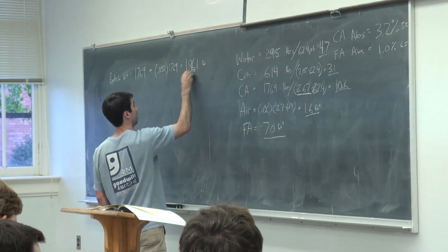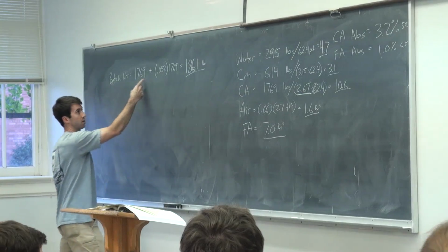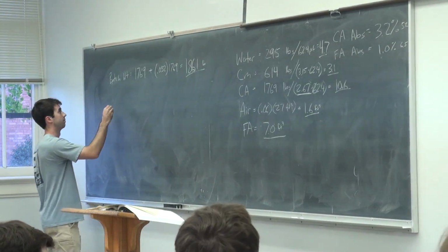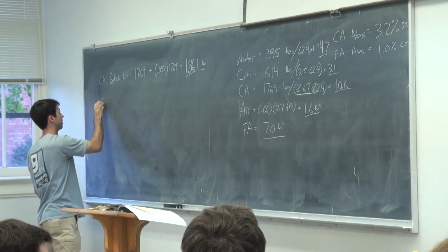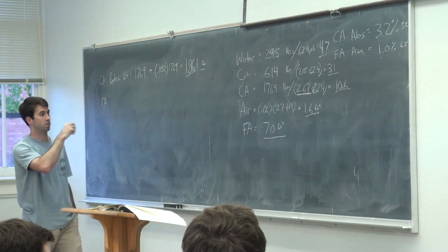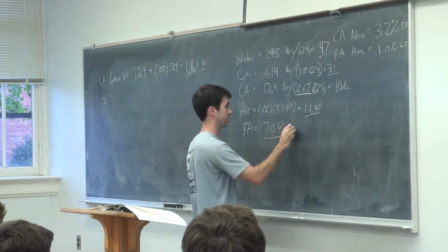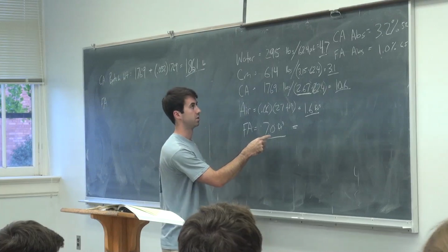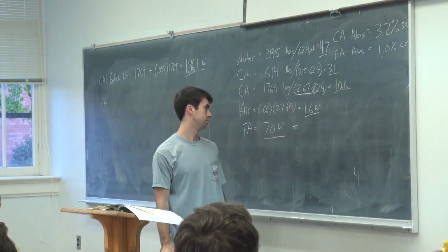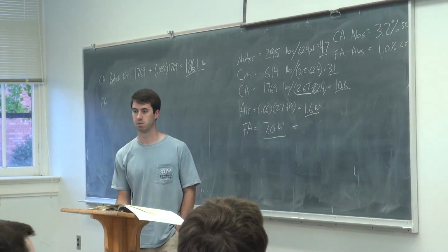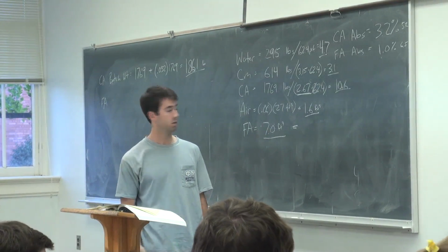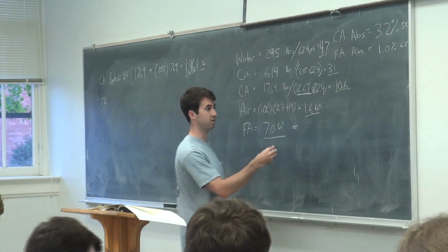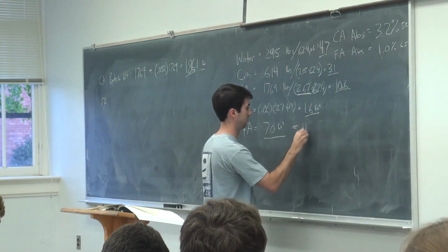All right. So to get that much actual rock, we have to batch that much out of the stockpile, and some of it's water. So we do the same for the fine ag. All right, what would this be in pounds first? It'd be 7 cubic feet times 62.4 times whatever specific gravity is. 1157.